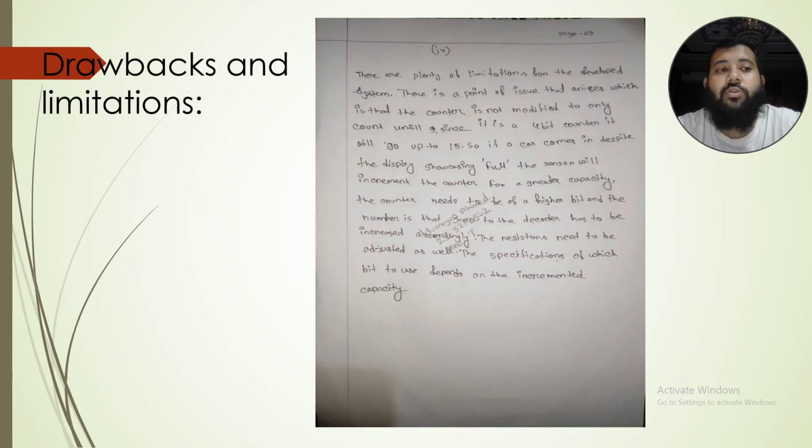And then the last part: drawbacks and limitations. There are plenty of limitations for the developed system. One issue that arises is that the counter is not modified to only count until 9; it is a 4-bit counter, so it will go up to 15.